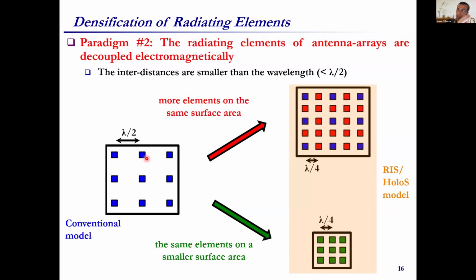For example, very large deflections in terms of reflections, the angle of reflection. But also, when you have 1 square meter or 2 square meters, you really want to utilize all the area, such that the effective area is actually the physical area. Also, because the more elements you put, the more the beamforming gain. Okay, so this also pushes us to rethink the communication models, because we need to consider the mutual coupling, and we need to exploit the mutual coupling if we want to get any gains from this structure, which makes things more complex, and also we need to use different models.